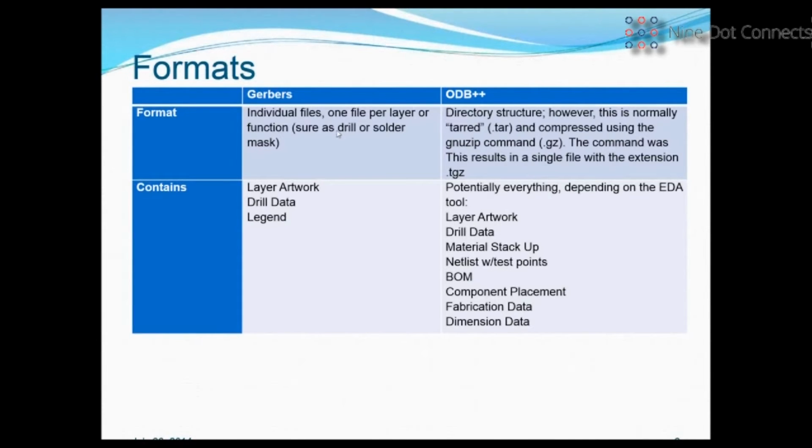They create one file per layer, and so if you're using something like Altium Designer and these other tools, you'll create those files. You can create them out of any of the layers in Altium. It can be a mechanical layer, your silkscreens, or the actual copper layers. You can throw pretty much all of those over to the manufacturer. They're pretty good about knowing which one's which, but you should certainly also provide them stackups so that they know which files to use.